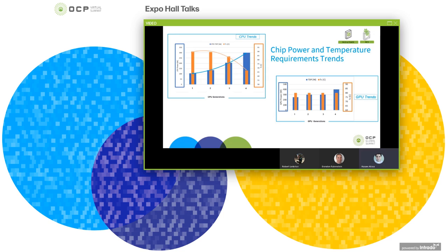Similarly, looking at the GPU charts, power has been going up constantly. And sometimes it is possible to have the power increase accompanied with a reduction in the required T-case due to power increase or die size shrinking, etc., which makes the thermal solution more challenging.